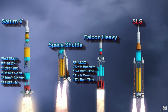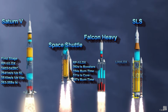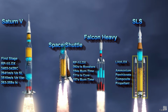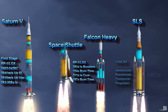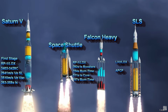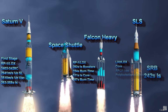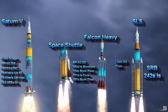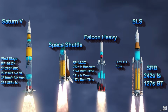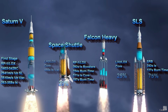Over here is the SLS. This rocket is burning hydrogen and oxygen in the core stage from this big tank through the Space Shuttle main engines, which are RS-25s made by Rocketdyne. And the boosters are burning ammonium perchlorate composite propellant, abbreviated APCP. This is the oxidizer as we explained above. The APCP is combined with polybutadiene acrylonitrile for fuel. They produce a specific impulse of 242 seconds, burn for 127 seconds, and provide most of the thrust for the Space Shuttle and SLS. The core of the SLS provides only 25% of the liftoff thrust. The Space Shuttle main engines provided about 29%.